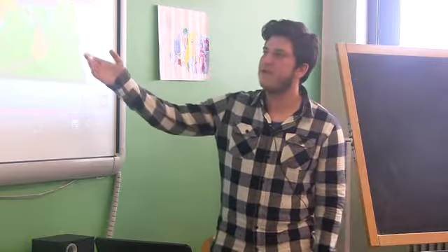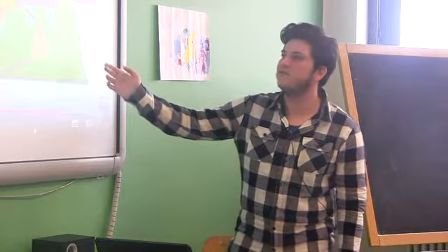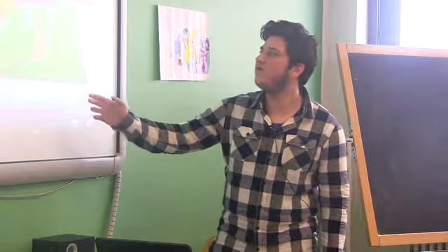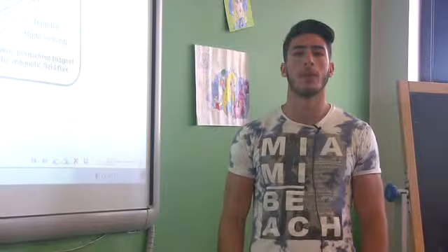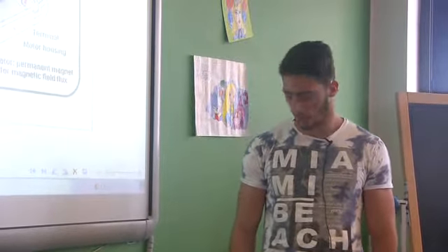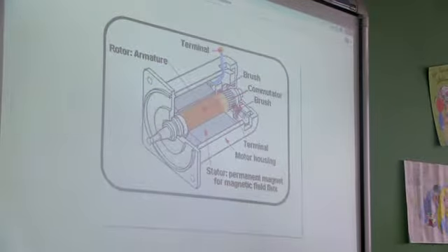If the coil is made to rotate continuously, electrical energy is converted into mechanical energy. Such an arrangement is called an electric motor. In a practical electric motor, the rotating part of the motor, or the armature, consists of several evenly spaced coils wound on an iron core as shown in this figure.